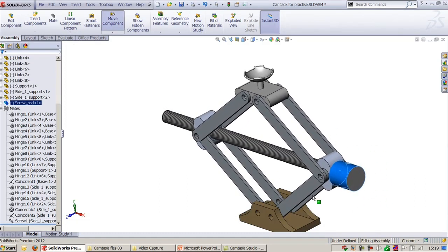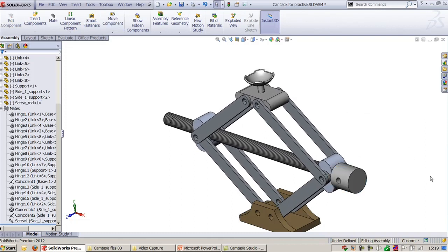You can also change the direction, which direction you want to move. And this is all about defining three types of mates in SolidWorks: standard mate, advanced mate, and the last one we had seen, the mechanical mate. I'm sure using all these three types of mates, any user can position the product in any complex geometry or any surface exactly, and understand the relationship between two components.